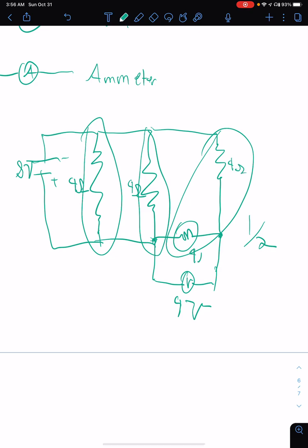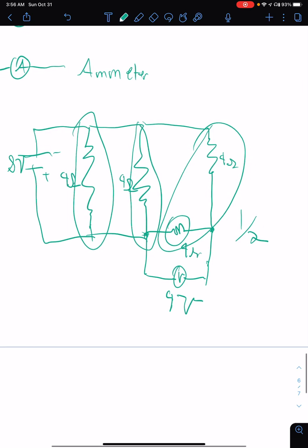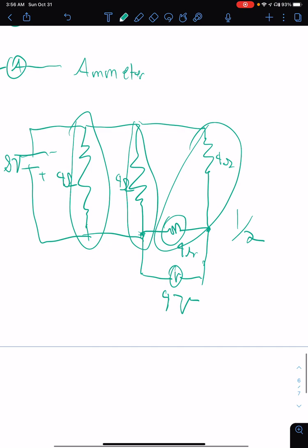And let's say they said all the resistors are the same, 4 ohms. How I would solve this now is I would combine these two, because it doesn't matter what the difference is between those, but the difference between these, and then I would go about it the same way, finding the voltage across this, which, as a matter of fact, should still be 4 volts, because it's halfway between equal voltages.